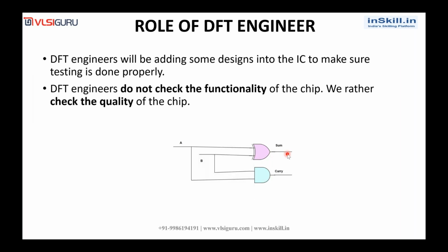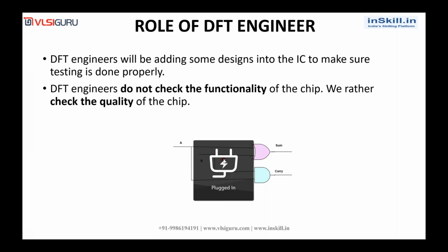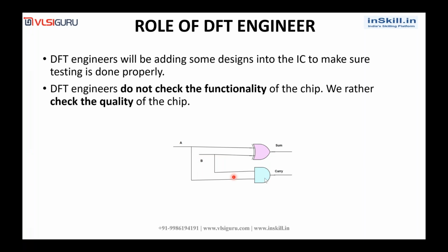DFT engineers will check on each and every net of the design whether there are any manufacturing defects or not. That is what will be done by the DFT engineer. DFT engineers do not check the functionality of the chip. We rather check the quality of the chip. That is, for example, in this case, we will be checking on each and every net whether there are any manufacturing defects or not. So that is the role of DFT engineers.